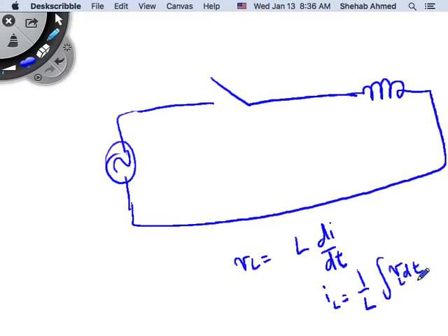When you're integrating, what you're doing is adding areas together. You have an area, then another area, and another area, and you add them together. So inductors are accumulating. Basically, inductor current is an accumulation of the shape of the voltage. So inductors don't allow current to change abruptly. And if current changes quickly, meaning this delta T is small, delta I over delta T.